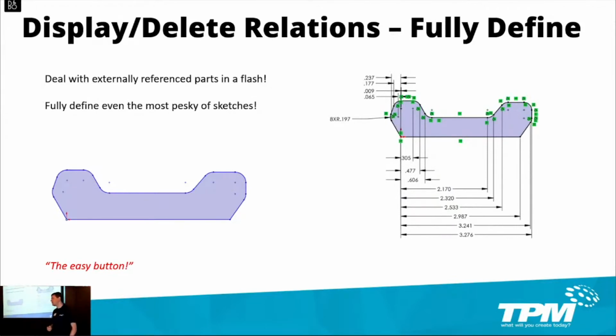Well, I mean, most people are going to find angles, not edges or theoretical sharps like that. If someone's drawing something, they're going to know it's on 45. Right. They're not going to dimension it like that. In cases like this, I would take some of my extraneous dimensions and I would delete them because this gets you 100% of the way. Right. But if you're seeing dimensions that you need for reference, those would be reference dimensions as opposed to feature dimensions. So you can get to a fully defined state without that reference dimension, but obviously if we're trying to machine that, we need that reference dimension to tell somebody how to fabricate it. So you would then add that as a reference dimension in the drawing.